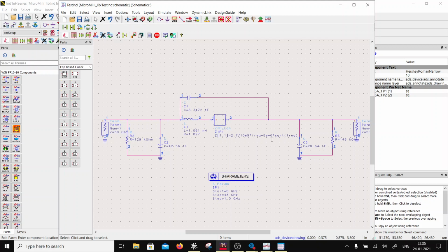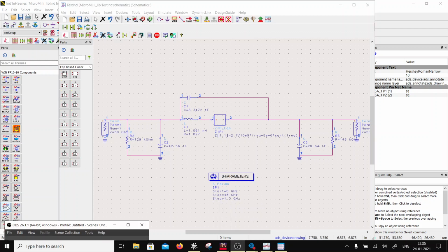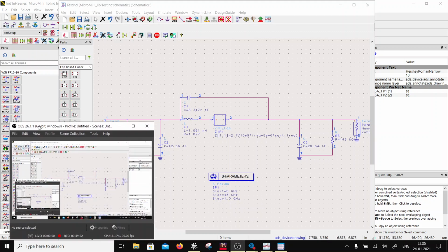And then if you want a model, you can fit it, but usually the idea is in your matching, the inductor value should match the circuit inductor value. That's how your layout is going to be the same as your circuit. So with that note, I am going to end this session here, right?